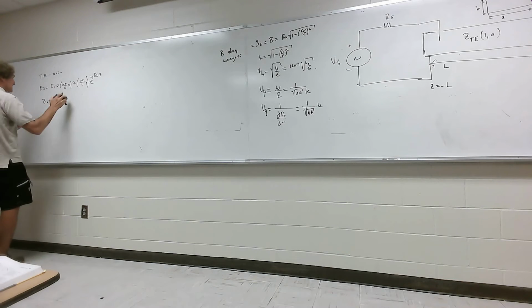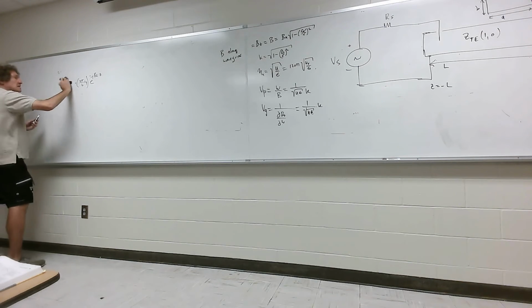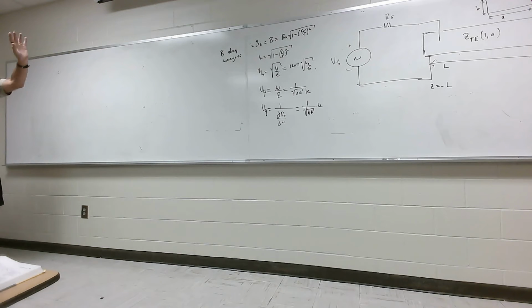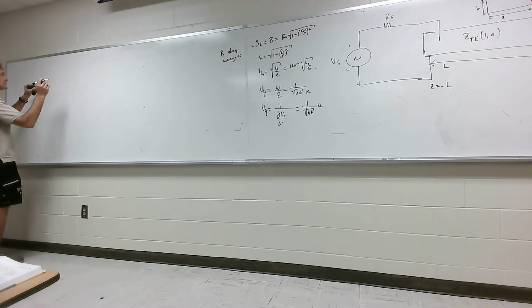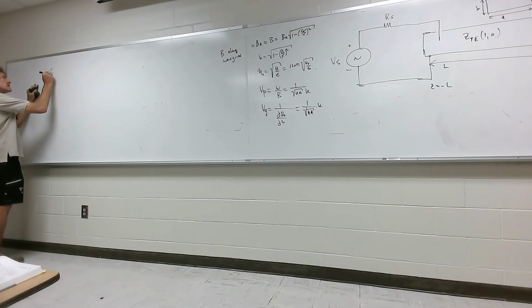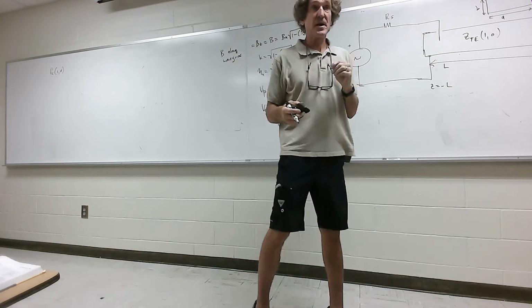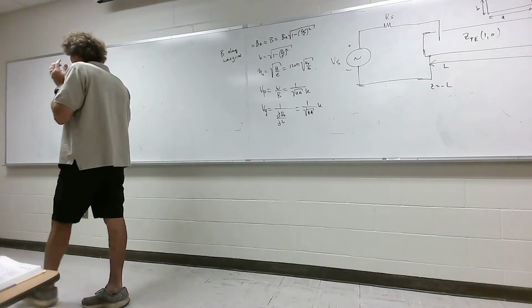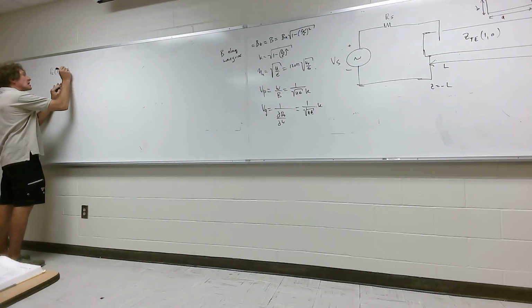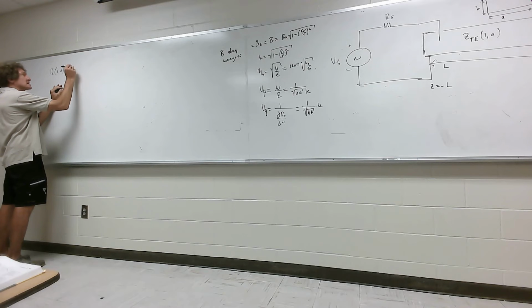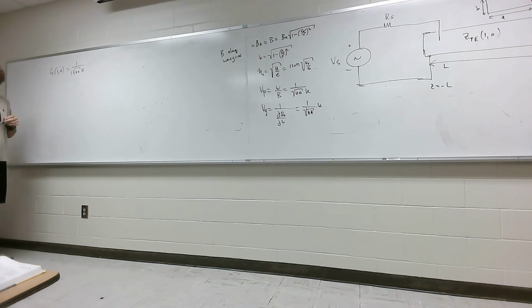So, when we come down here, I'm assuming it's operating in the TE10 mode. First thing, we get the cutoff frequency for the TE10 mode with my guide. Really, if I give you a problem like this, I'll give you dimensions a and b, and you're going to figure that out for yourself. It would be equal to simply 1 over 2 square root of mu epsilon divided by a. That would be the TE10 cutoff, all right? Whatever it is, doesn't matter.